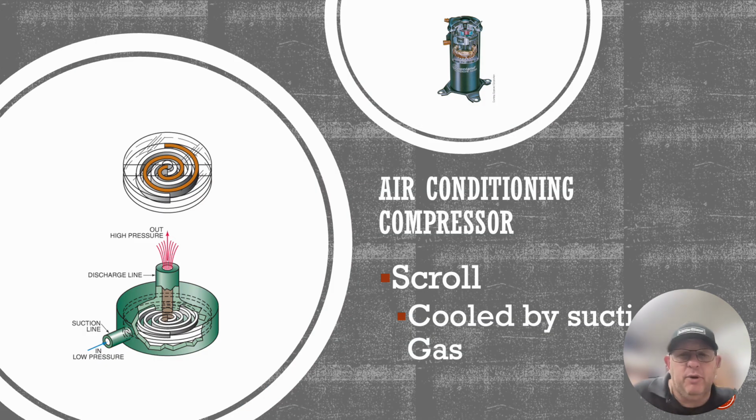The last compressor I want to look at is the best compressor that we have in the industry. They are coming out with modulating scroll compressors, so you're going to be seeing it in that industry quite a bit more. And it is the scroll compressor made by Copeland. There are knockoff brands made by about every manufacturer out there, but Copeland was the first one to come out with the scroll type compressor.